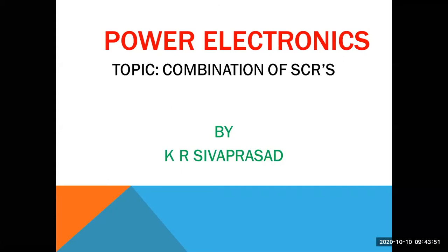In combination of SCRs, the series connection of SCRs or parallel connection of SCRs are combinedly called a string. That is, the entire set is nothing but a string. So a string is nothing but the combination of all the SCRs, whether it may be series or parallel or the combination of both. In some cases we need both, to meet the desired requirement of both voltage and current rating. In those cases we need series and parallel combination both.